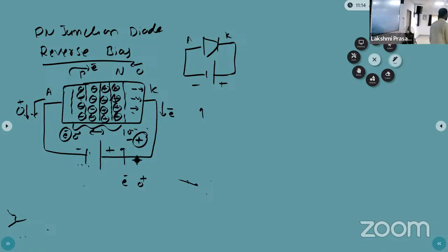will current be present or not in the reverse bias? Present. On what basis is that current present? Breakage of covalent bonds. Due to the newly generated electron-hole pairs, current will flow, as electrons and holes can move from the p-type to n-type and n-type to p-type.